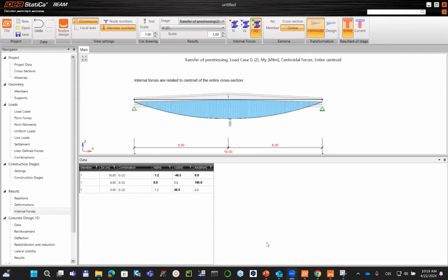Okay. In some cases, due to a large amount of pre-stressing reinforcement, we have large negative moments at the transfer, and we control this bending moment using mild steel. Using mild steel in most cases, because we do not want to add top fibers pre-stressed, and it's cheaper. Generally, yes, this is an approach that can be used.